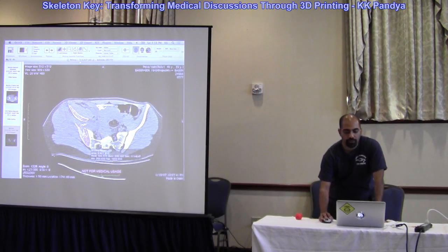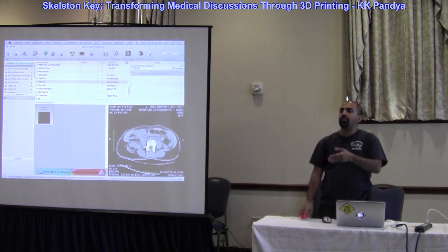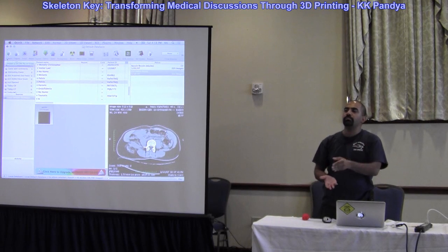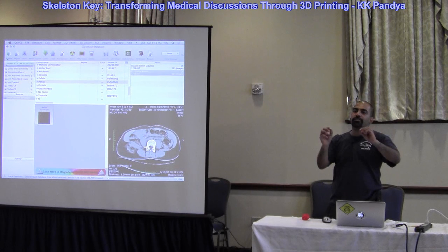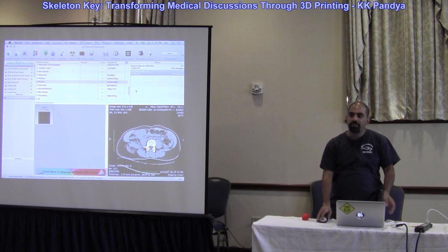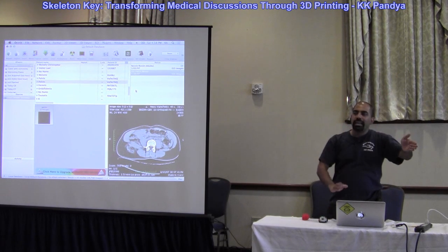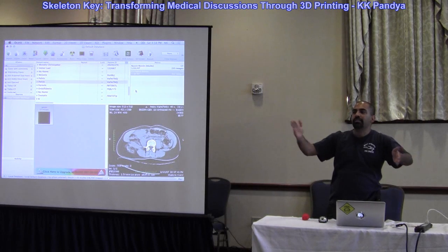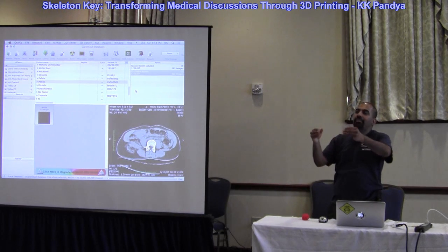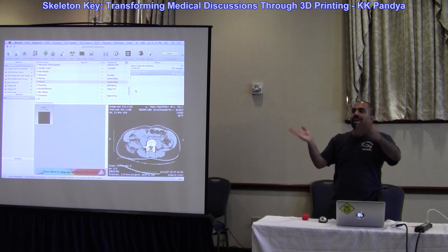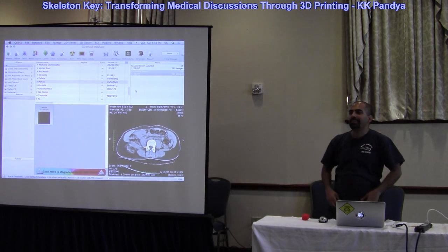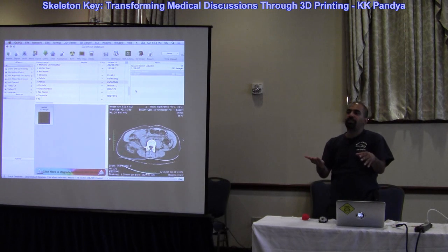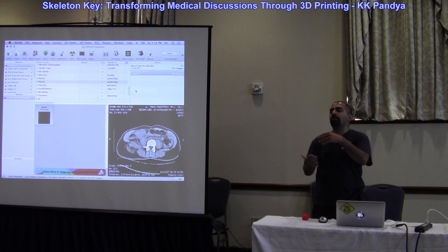Since the metal shows up on a CT as denser than bone, you could set an upper bound: define this region of interest as bone, but less than metal. And you could also define the metal as a different polygon set and print that as a separate 3D print, and then put it together. Or with the dual extrusion setup, you could print those as one integrated piece.